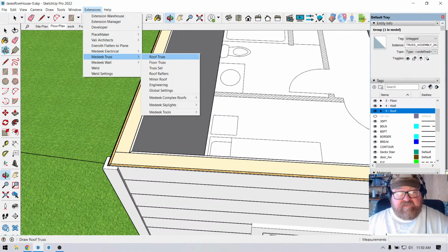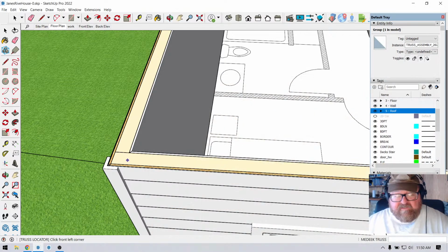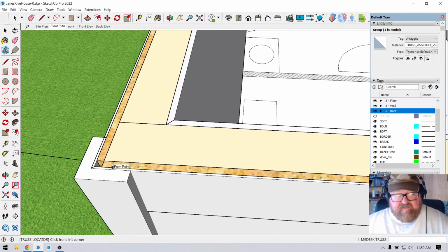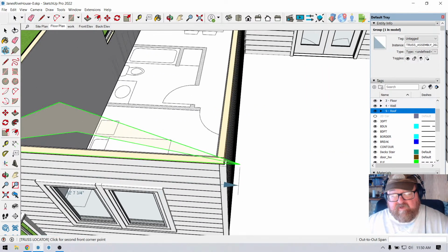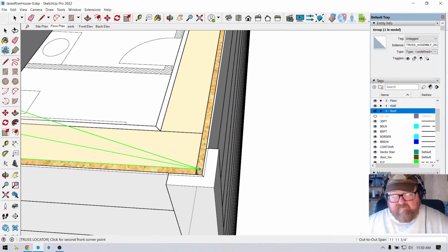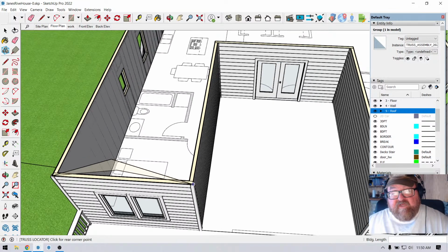And coolly enough, Nathan has these scissor trusses. Dang, I thought I saw them. And they would go on that point right there because they have OSB, they have sheeting on the gable end too. So you want to line up your framing. You want your trusses to sit right there. And then the same thing back here.